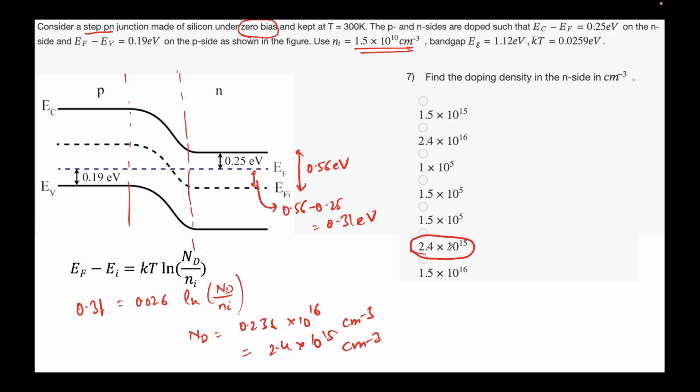So as I told you, we are doing nothing new here, the sample is at thermal equilibrium on the N side, in fact throughout. Now on the N side we just put this formula which we have seen in the last class from the Fermi level, or you can just recall your expressions that N equal to Nc e to the power Ef minus Ec, and all those expressions, it's given in your notes, so there's nothing new happening here, right?